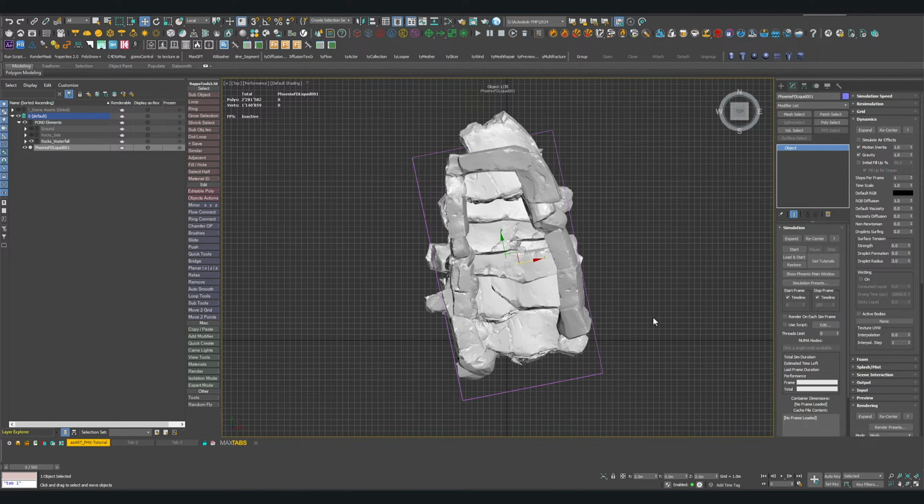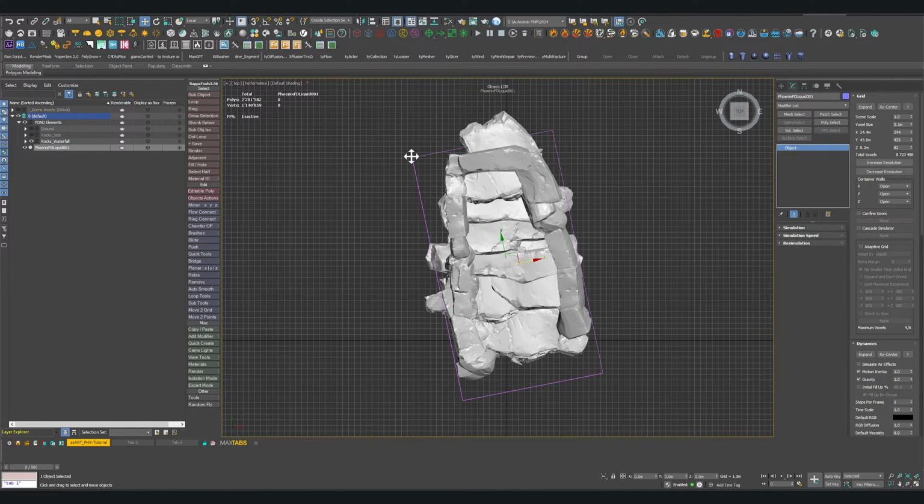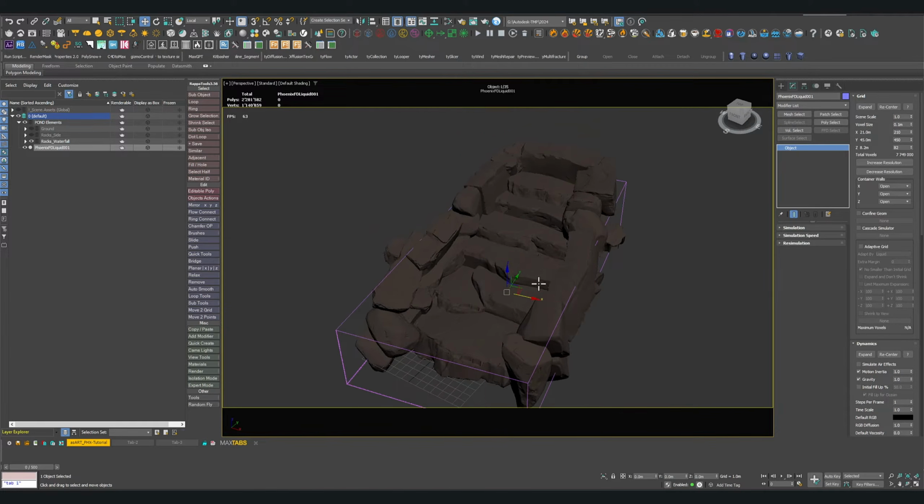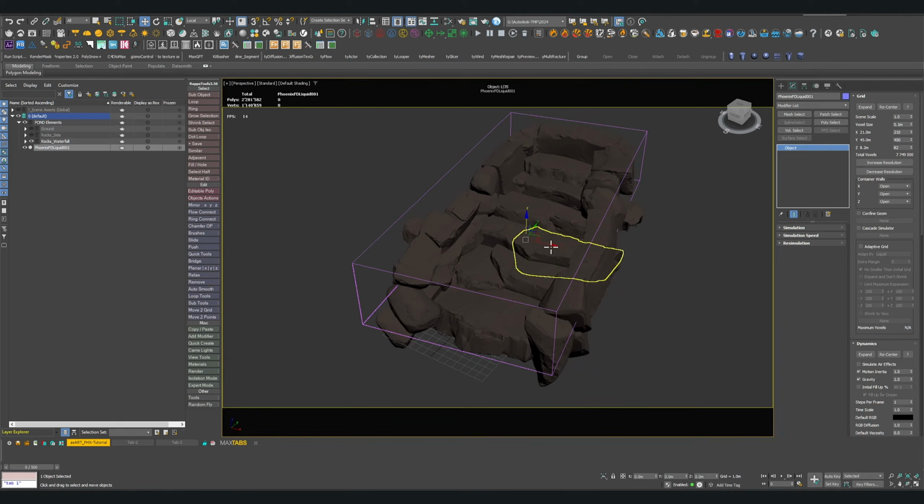And now if you want to change the size of your grid, it is important that you do that inside of the grid rollout here and not just using the scale or something. So just go into the rollout and set that up like you want it. So now we have about 200. Let me set it to about 210 or something. And the y-axis I'm gonna set it to 450. So something like that.